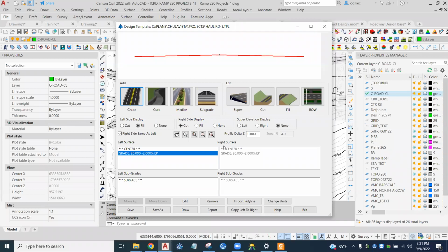The berms would be, I think, 3 feet high, and so the base would be about 3-to-1 for the berm. Alright. So are the berms always there, or only on one side? On one side, the side facing the pit. All right, so I'm going to turn this right side, same as left, off. Okay, let's see, what can I do with this? Copy left to right, so now there's that one, so 20 feet.